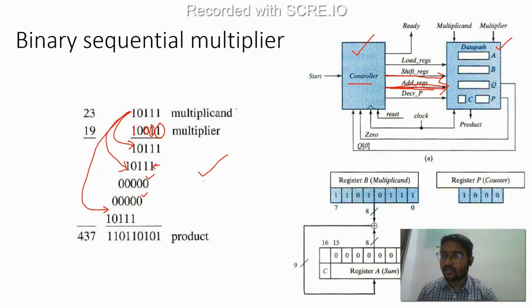This is one of the procedures. Instead of this, let's call these partial product 1, 2, 3. Depending on your number of multiplier bits, if your multiplier has 10 bits, you will have 10 partial products. If it is 20, you will have 20 partial products. So you need 10 or 20 registers to store each partial product. Correct? That is just one way.